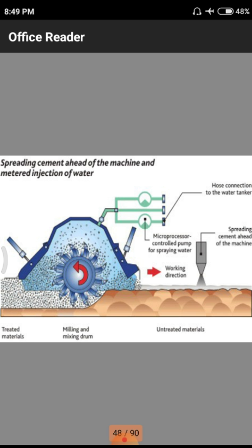In the previous lime case, a spreading roller is there. The total spreading roller is moving on the surface of the ground. Automatically that spreading roller will carry all the lime content to the soil in an even manner. But in this case, the equipment grinds the total cement content and the soil content.